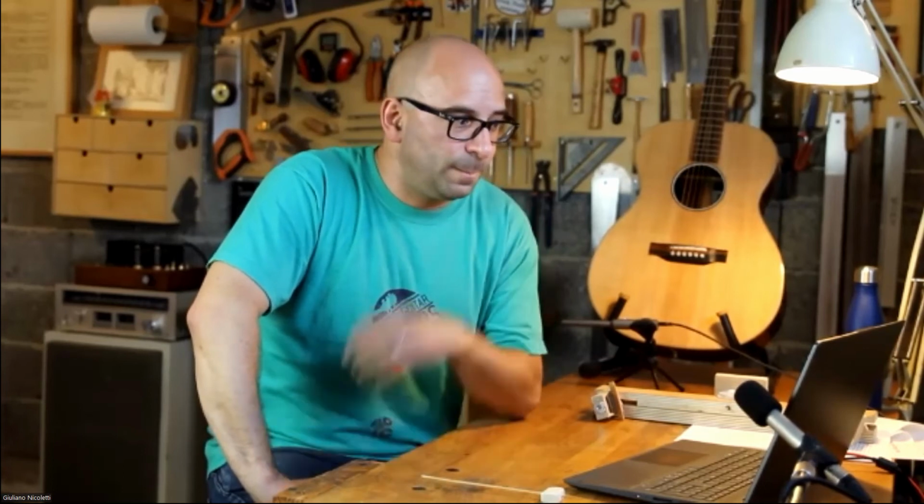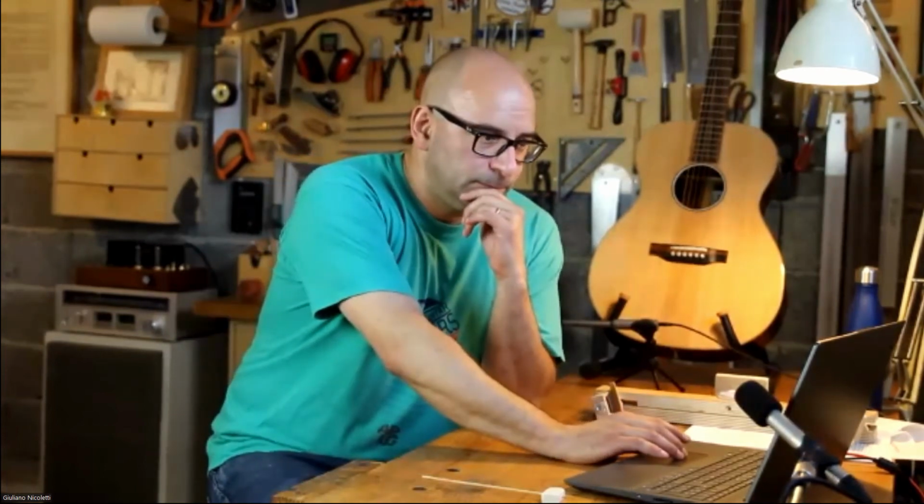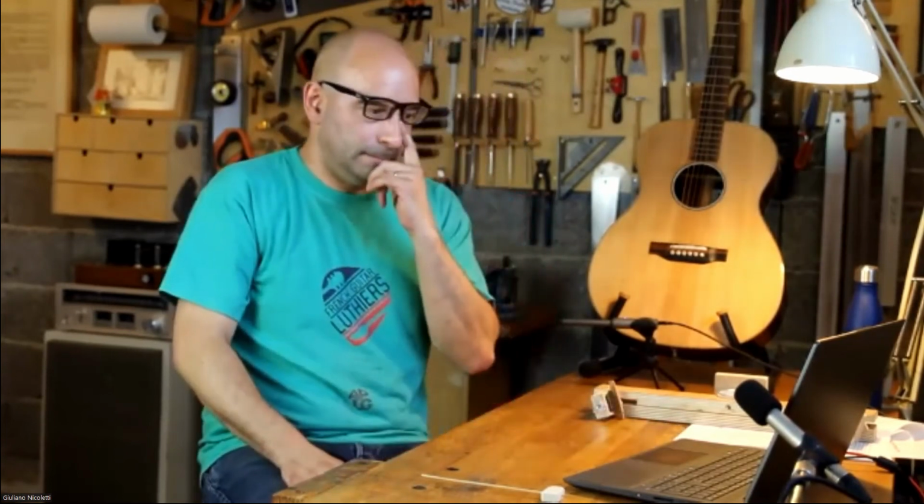I would say that we achieve that by making the soundboard thinner gradually as it gets to the edge, and also by making the bracing lower as it gets to the edge. So rather than a sudden thing like a route, it's more gradual. The heaviest, stiffest part of the soundboard is around the bridge, and the lightest part is around the perimeter. Yeah, it's true. Thanks.